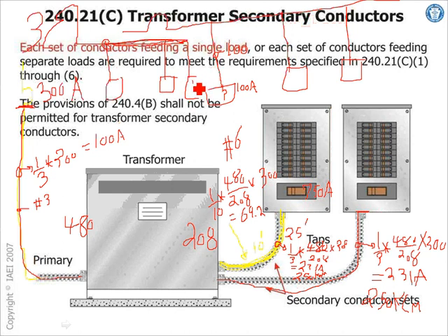Basically, this application here, except outside. No limitation. If you have a transformer outside, and you tap the secondary, take it from the secondary side, go 300 feet, 100 feet, 200, whatever. The only condition at the end here, you have to land a circuit breaker or a fuse that protects the conductor at its own ampacity. So they're so relaxed when it comes to outside tapping a secondary of the conductor or a feeder. Very relaxed.